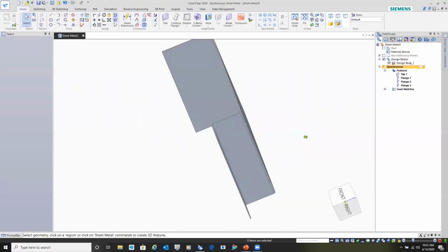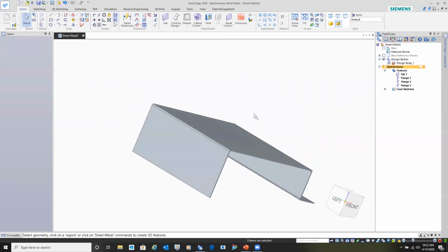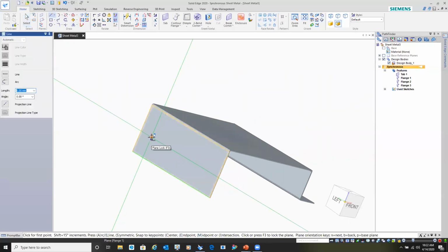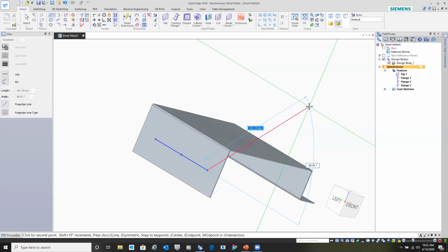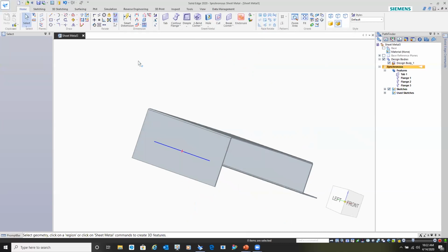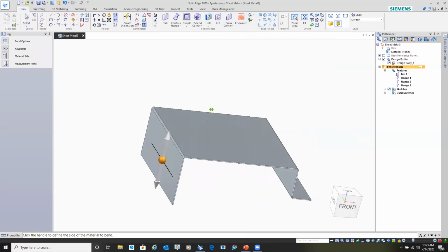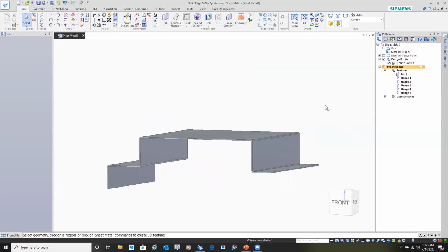Likewise, we can go here and draw another sketch right on this face. Now notice I'm not going to lock this face. I'm just going to go ahead and draw it because it recognized the face by itself. And I can draw on that face. That was the other method for grabbing faces. And I'm going to go up and select the jog command. And with the jog command, I select this. And you'll notice I can pull out the jog and position it like so.